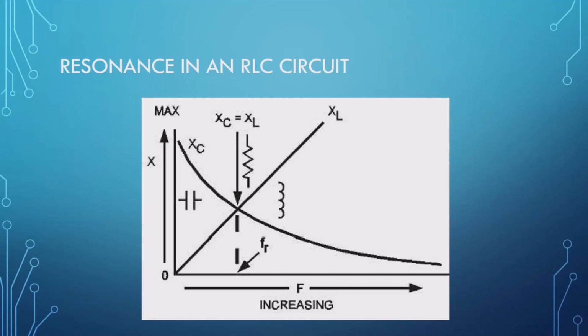And that's based on the mechanics of how a capacitor works. It charges the plate, and then when the power is removed from the capacitor, it discharges. But we also use capacitors to block DC noise and other low frequency noise in circuits, using that same principle. When we're talking about filters, we're going to use it to block lower frequencies until we get to our desired frequency.